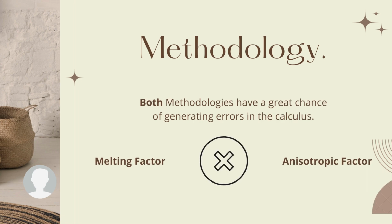Both methodologies, proposed and final, have a great chance of error because of the melting factor and the anisotropic factor, because we are assuming that the filament is isotropic. This means that all the properties are the same in every point of the material and in every direction, which is not true. And we are assuming that the filament is not going to melt at a certain temperature, which is again not true. We're going to review these factors in more detail later.